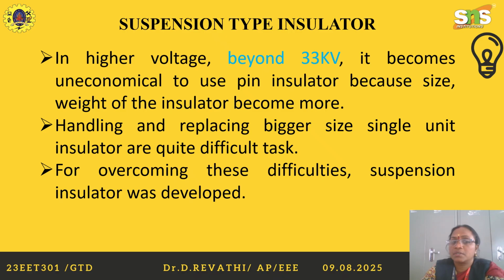It may be uneconomical for pin type, and for the bigger size of the unit, replacing is difficult. These are the difficulties we meet in pin type insulator. To overcome this we go for suspension type.